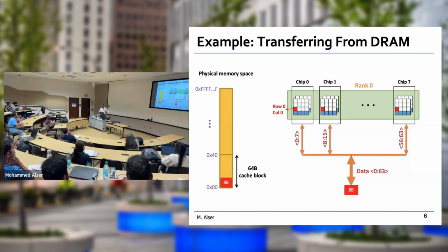So I send the next clock cycle with a different address this time. The address is the same in the row, but different in the column. So I still need to fetch that row. However, we discussed last time, if the row is not changing, what should I do? I already keep that row in the row buffer, and I don't need to close the row, so I don't need to return it back.